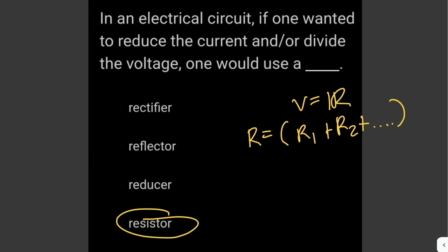While in a parallel circuit in which resistors are aligned in parallel and the current has multiple pathways available, the current through each resistor is only the same if the resistance of the resistors in parallel is the same. Therefore, the total resistance in a parallel circuit is the reciprocal of the sum of the individual reciprocal resistances.